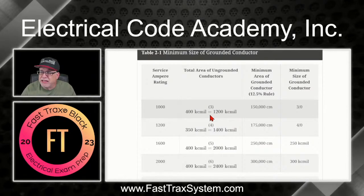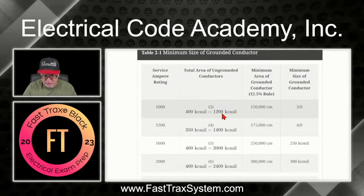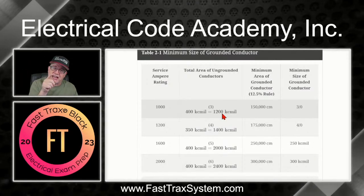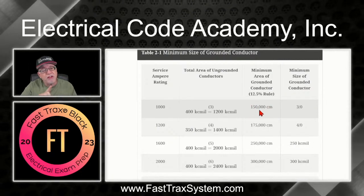So we have to take that 1,200, which incidentally is 1,200,000 circular mils, or you could take that 1,200 times 1,000 to get your 1,200,000 circular mils. And we multiply that by 0.125, which is the decimal equivalent. Or you can take the 12.5 and move the decimal 2 places to the left to make it a decimal, which is much easier for your calculation. And that's going to end up being 150,000 circular mils.